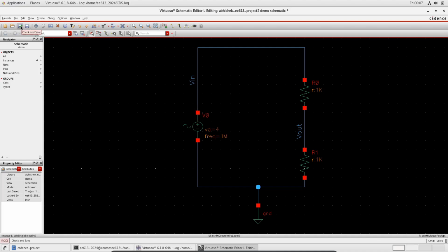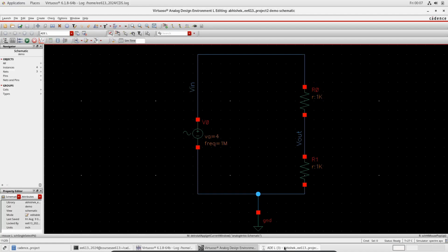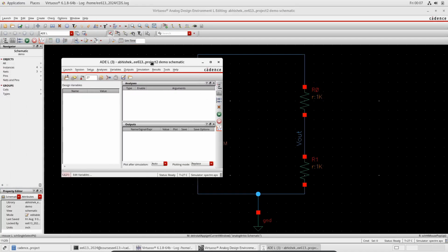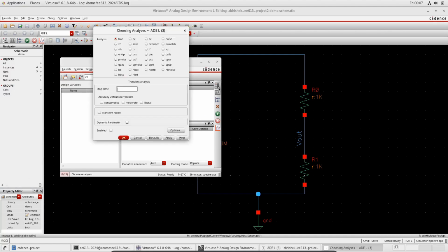Now I will click on check and save. After this I will click on launch ADE L. Now this is my ADE L window. Now we will click here, and from here you can choose whatever analysis you want to run, like transient analysis, DC analysis, AC analysis, noise analysis, and so on. In this video I am going to cover transient analysis, which is selected by default.